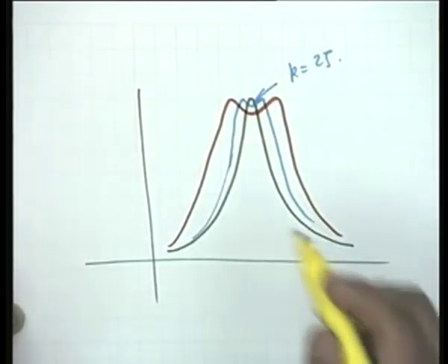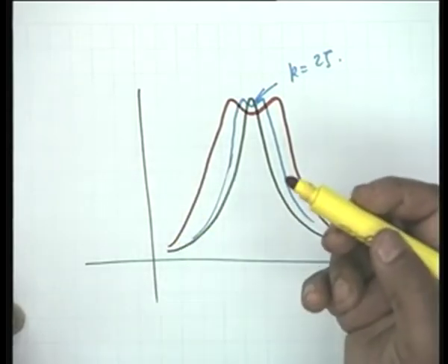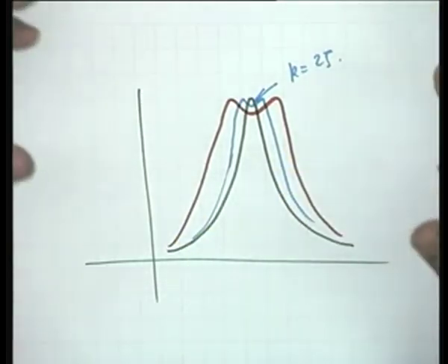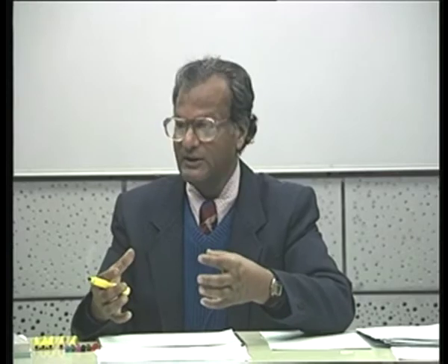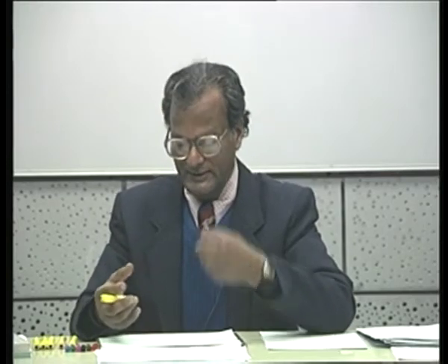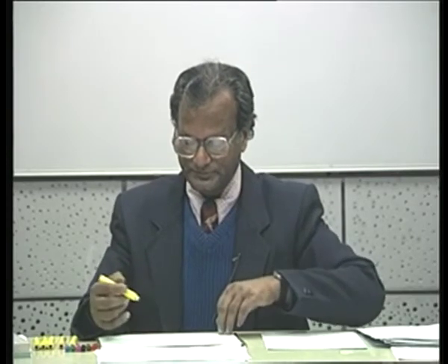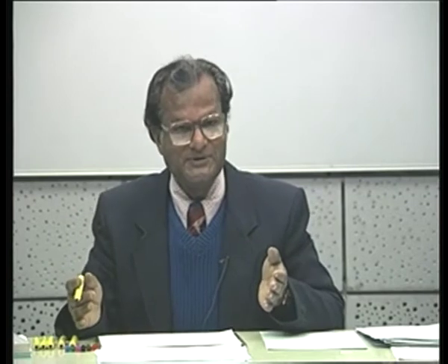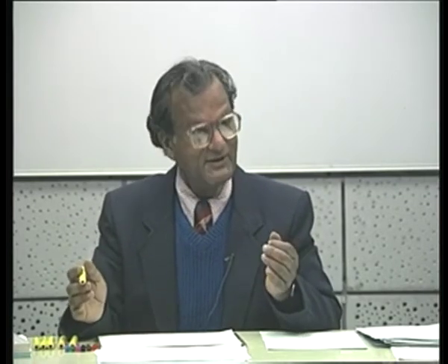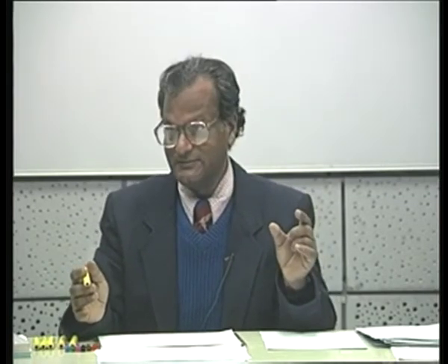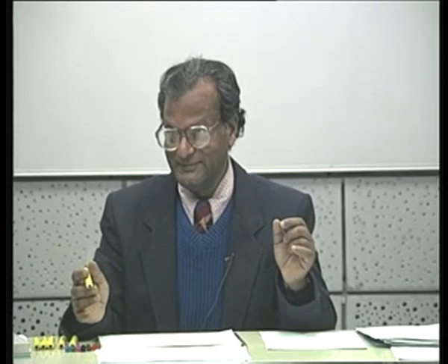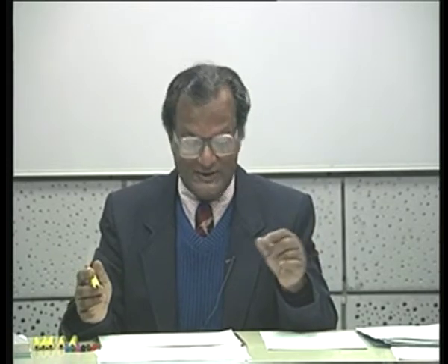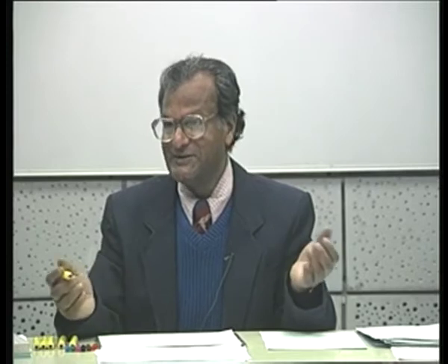Okay, and then this phenomenon goes on as we make the coupling tighter and tighter, as we bring the coils closer and closer together. The dip in between and the separation between the peaks increases. So for the same dip, can we increase the separation between two peaks? No, not with the same coils, you will have to change the coils.